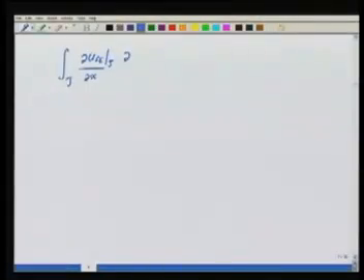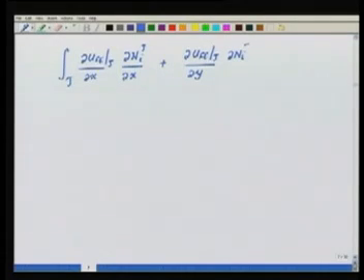So what does this 3 by 3 stiffness matrix correspond to? Just like we have done earlier, let's talk of the integral over the element tau of del UFE over the element tau by del x. Now here, instead of V, we are taking the basis functions which are non-zero in this element, which are nothing but del Ni in the element tau by del x, plus del UFE in the element tau by del y times del Ni in the element tau by del y.